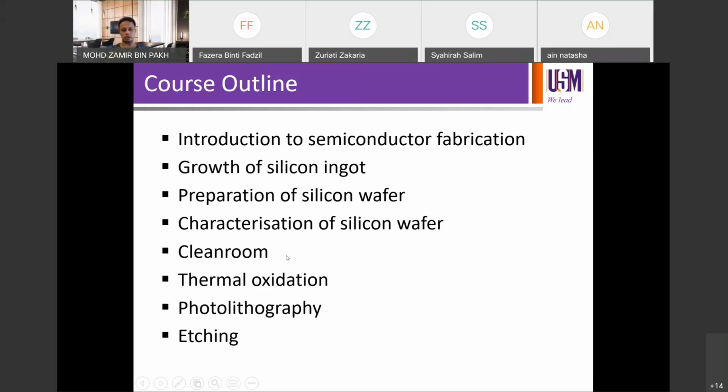You know the do's and don'ts in a clean room with different classes. You know that perspiration is one of the main contributing factors to the contamination problem in a clean room, right? Our walking, our movement, handling of the wafers, and cosmetics and perfumes and stuff like that, right? Then we've discussed the very first process, thermal oxidation. To do pad ox, field ox, you can use dry ox, you can use wet ox, depending. You can even mix dry and wet depending on the processes that you want, the qualities you want to get on your device.